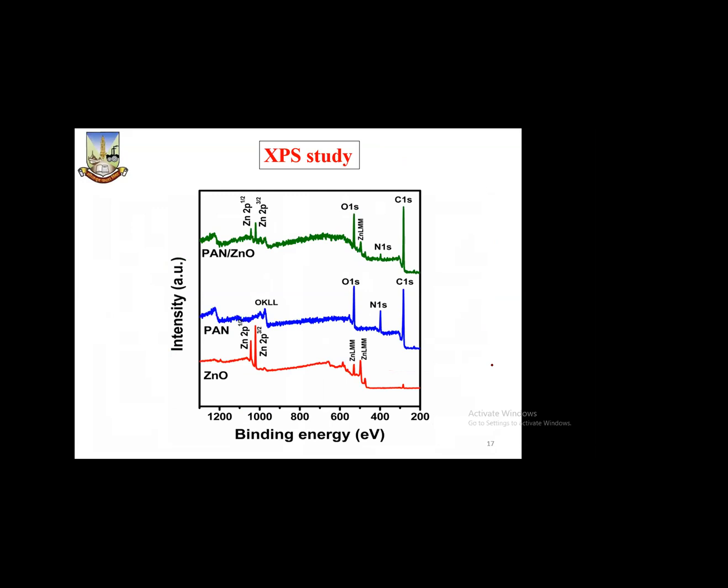This is the XPS study. The XPS study itself again shows the formation of the complete PAN zinc oxide nanofiber in the presence of PAN and zinc oxide. The binding energies are in adherence with the standards which we required, with the presence of the inner and outer layer shells.